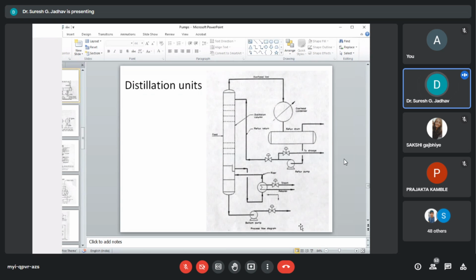The PFD of a typical distillation column with bottom pump, thermosyphon reboilers, overhead condenser, and reflux drums is shown in this sketch. During the normal operations, the pump transports the liquid in equilibrium. The arrangement should be such that the nominal pipe size requirements of the pumps are satisfied.